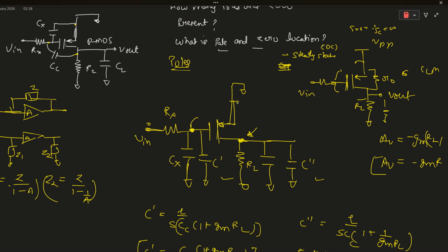If there is only a capacitance and no resistance at a node, we cannot say a pole is there, as the R in parallel with C is infinite, so the pole frequency would become zero. So we can say there is no pole; we can't say the pole is at the origin. That is wrong.